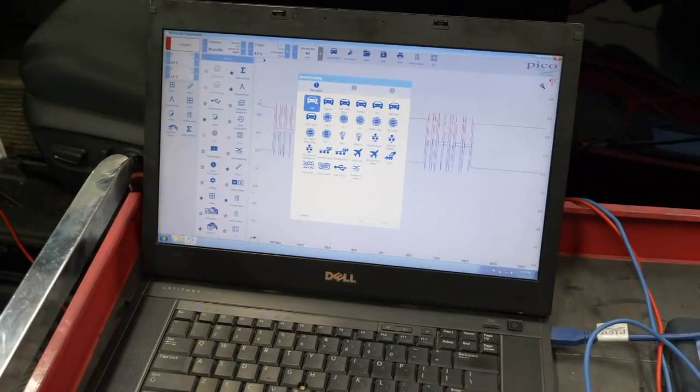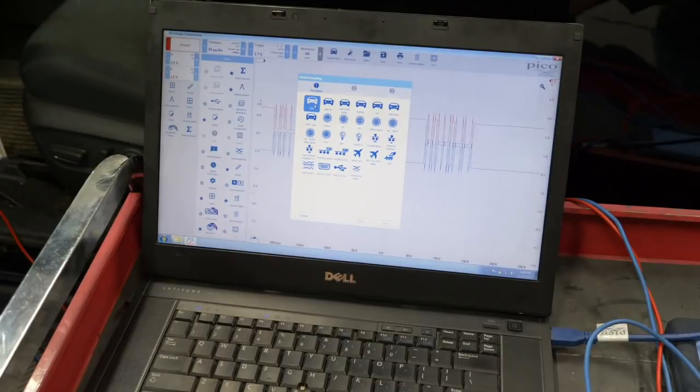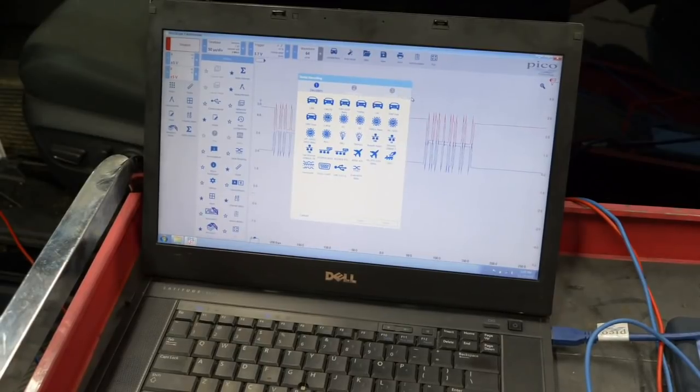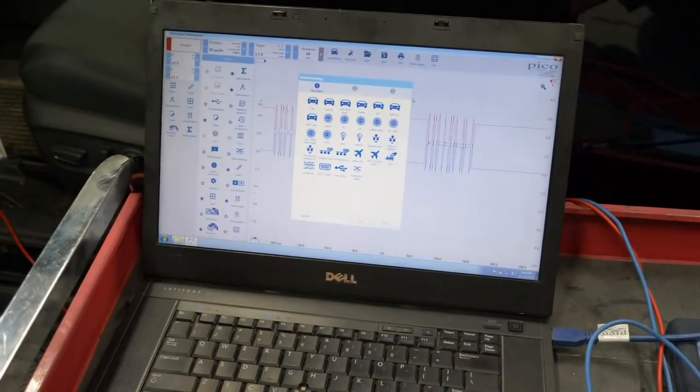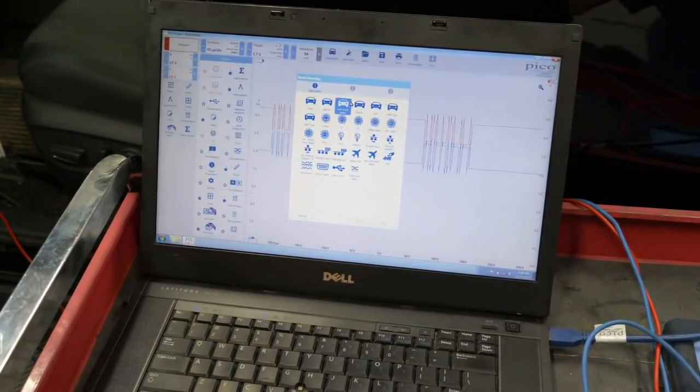Oh, okay. I noticed that there isn't a lot of the older networks that I described, things like J1850, things like that. Is that just not available on here, or can those not be decoded, do you know? That's a good question. It's my understanding that some of those are not necessarily lower layer networks. And so those might be a higher layer. We'll kind of get into the network layers on the whiteboard after this. So we'll touch on that a little bit more there. I could be wrong, but many of the things like OBD, for example, you don't see here. That's because it's on a higher layer.